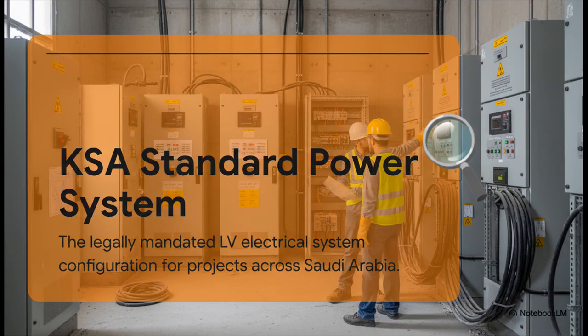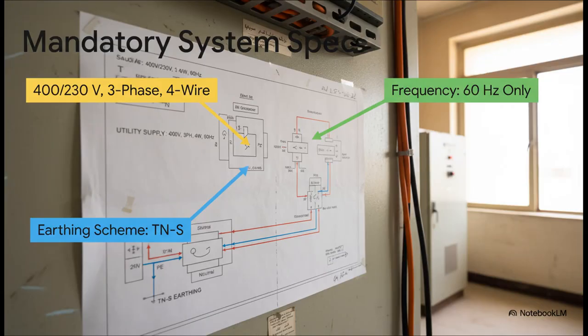Okay, so with that hierarchy in mind, let's look at the actual system you are required, by law, to use. And I want to stress that this is not a design choice. It is a legal mandate from the SEC and SBC. These are the numbers that have to be on your single line diagram. No questions asked. We're talking 400/230 volts, 3-phase, 4-wire.